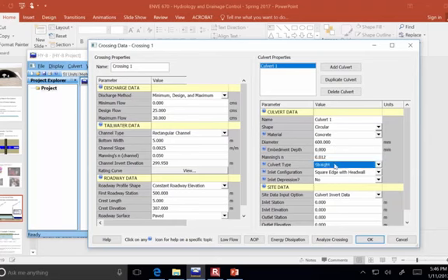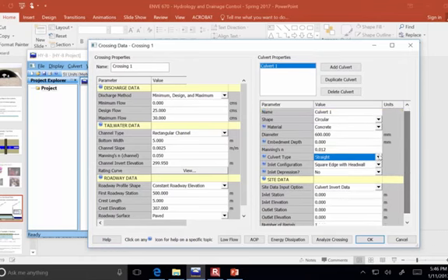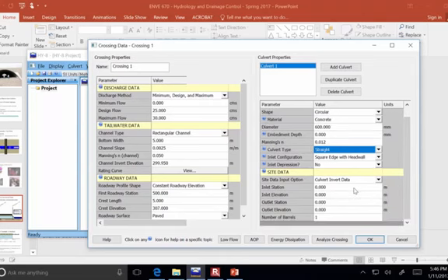So I'll just leave these all with the default options. It doesn't change the performance very much if you change around some of these parameters, like whether it's straight or side tapered. You can play around with it. In fact, I ask you to do that on the homework assignment, to see how much it changes the flow conditions, but it doesn't have a huge effect. So we'll just leave the default options for these things, but we do have to tell it how long is the culvert.